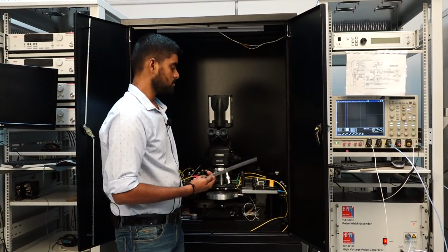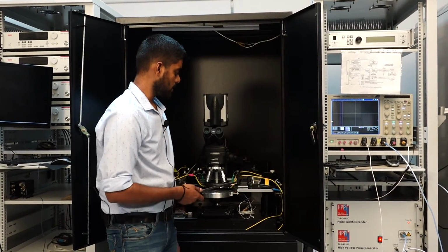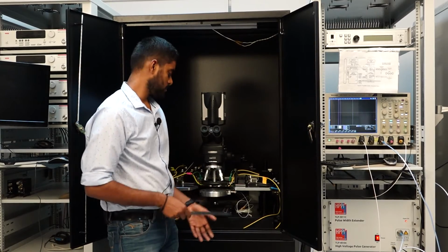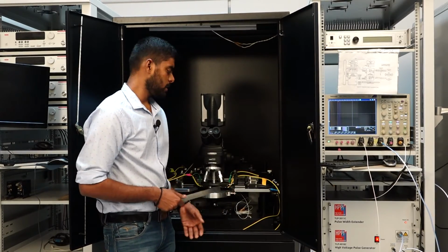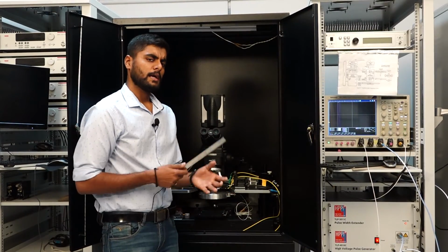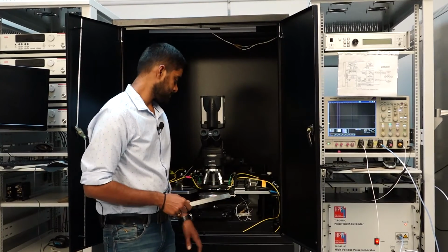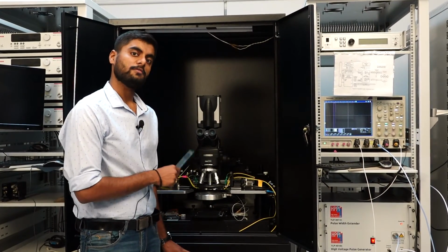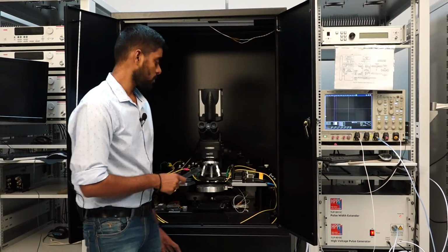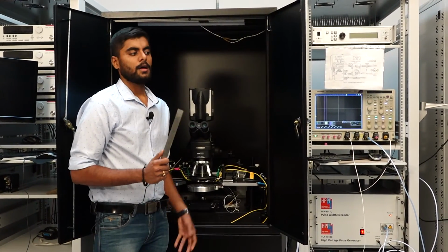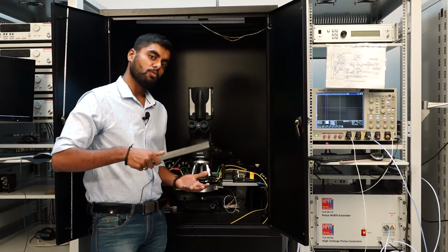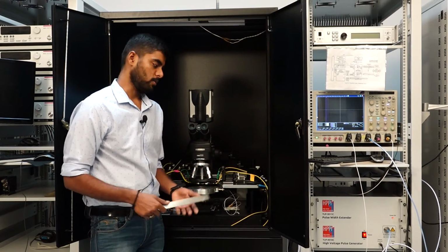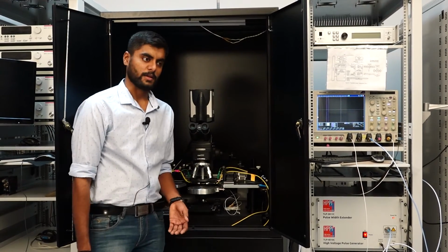Another thing that I can mention is that this microscope is movable. You can actually move it in the Z direction. You can move this chuck in the XY direction, and you can move the whole assembly to whatever configuration you like. The devices that are rested here are on the vacuum as well. So basically, you have these small holes here on the chuck, which make sure that your device does not move along in the measurements whenever you don't want it to move along. So that's why you have these vacuums as well.